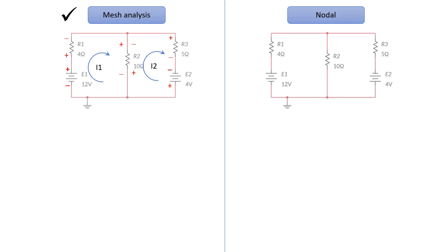So we will then apply Kirchhoff voltage law in loop 1 and loop 2. So you'll have the first voltage drop plus the second voltage drop plus the third voltage drop. Adding these three voltage drops in this loop together, we will get equal to 0. Then for the second loop, we will add the first voltage drop, the second voltage drop, the third voltage drop. If you add these together, we're supposed to get 0. So let us start with loop 1.